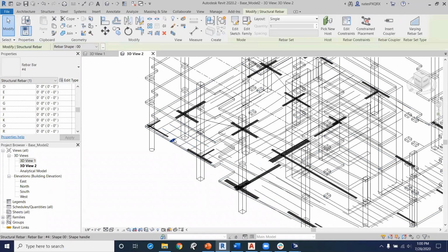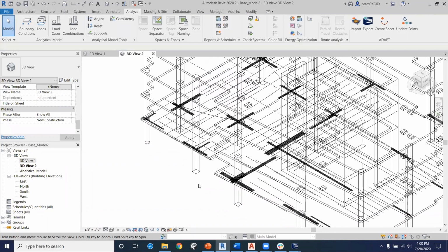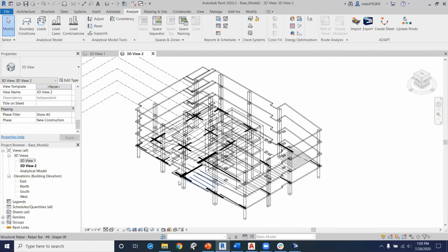So if I click this, you can see this is tendon number 7, and it even tells you the total force. So in this case, 53.4 kips was the 2 strands that we added in the banded direction. So this could save you a bunch of time on creating your drawings and for your submittals.